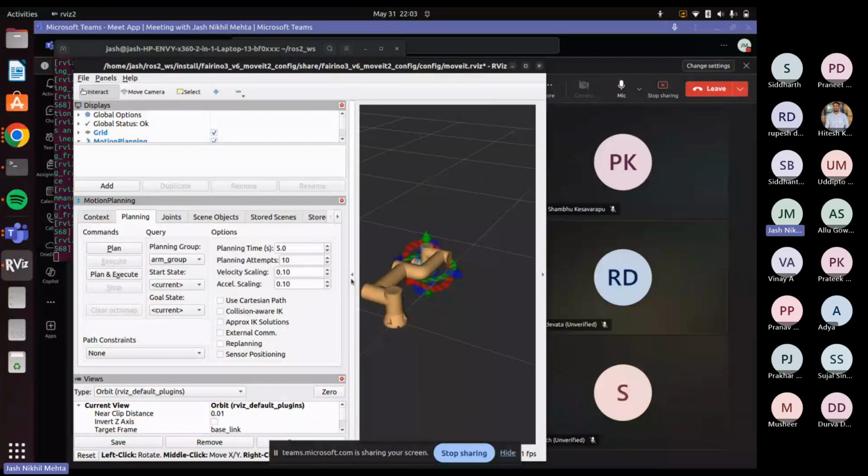From those STL files, you can create Xacro files, .xacro. Those files convert the STL files into coordinate systems, so they tell what the coordinates of the arms are, what the coordinates of everything are. And from those Xacro files or URDF files, both are acceptable, you can create configurations and then simulate the robot. Are you all with me so far?